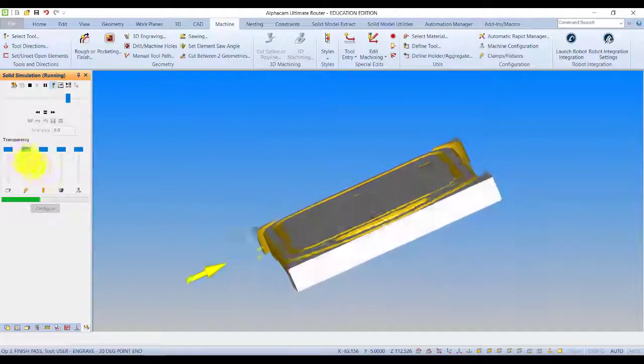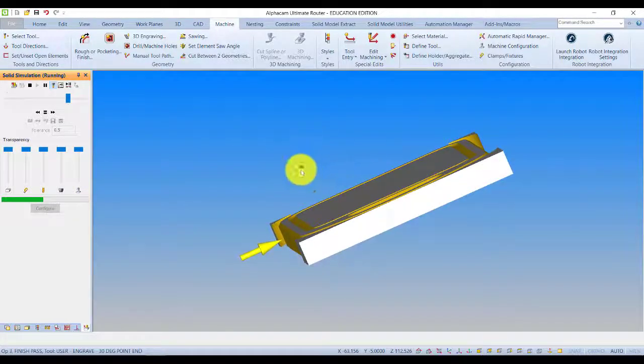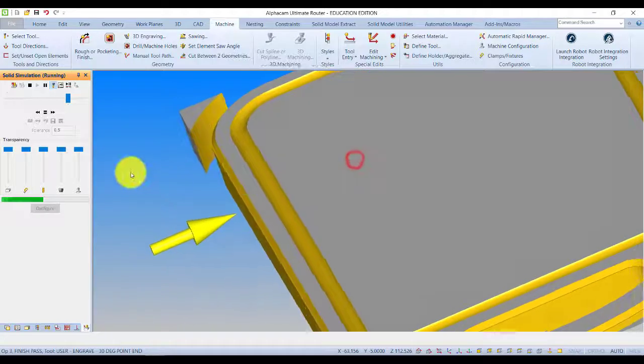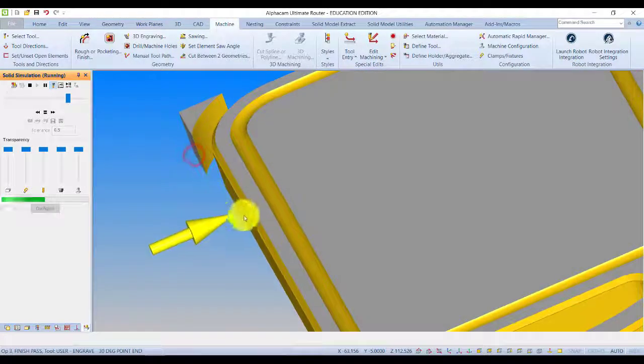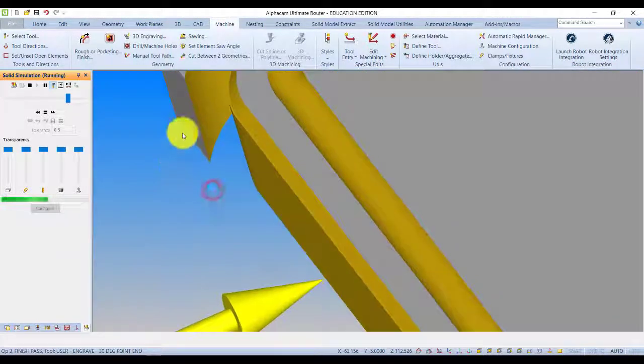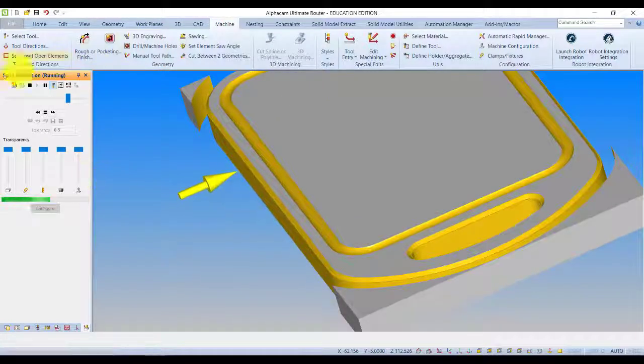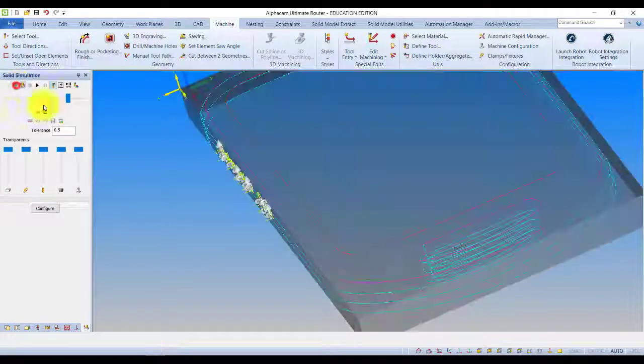Now, I made a small silly mistake there myself. I'm after realizing that because I sliced through the work volume there at the edge, it's only cutting below the depth of that grey face. It's not cutting there. So you have a couple of things you can do. You can either go back and edit the block itself. I'll stop the simulation.